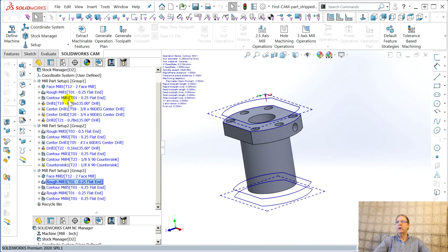And oh, here's a warning. Go to the perimeter. Where is it here? Here? Yeah. The fact that it shows it starting up here going, it would cut all the stock off, which means how do you hold it in the vise? This would crash into the vise if you let it. Danger Will Robinson. But even sillier, over here, it does a rough and a contour all in air because it's all been cut off on the top setup.